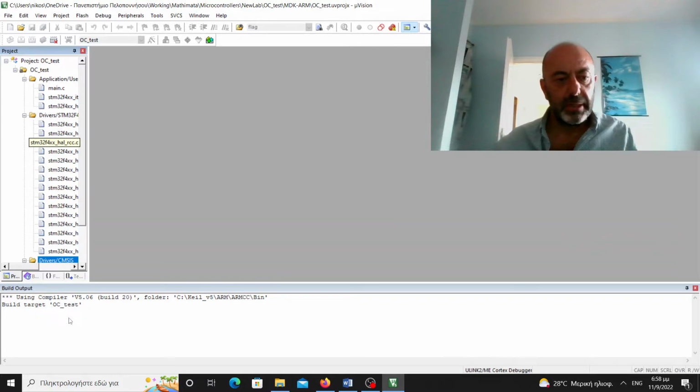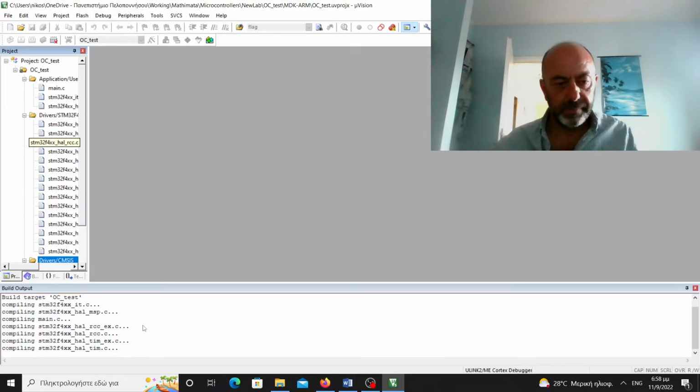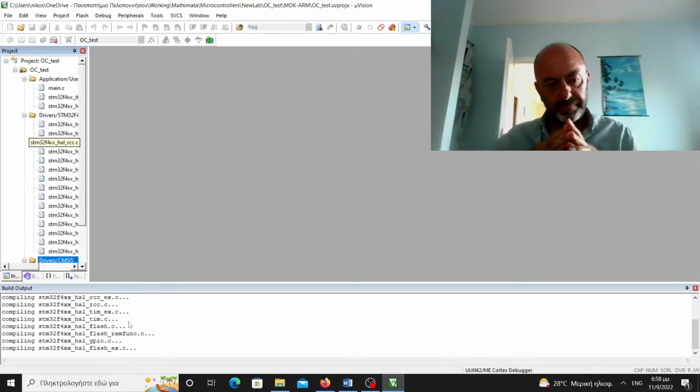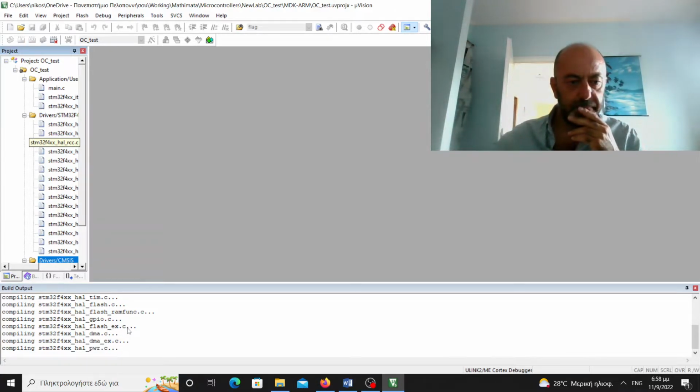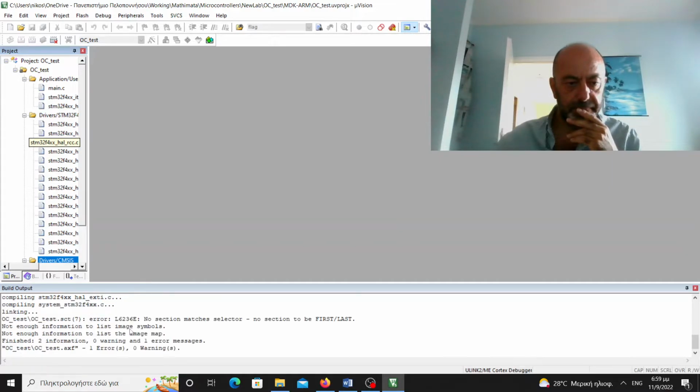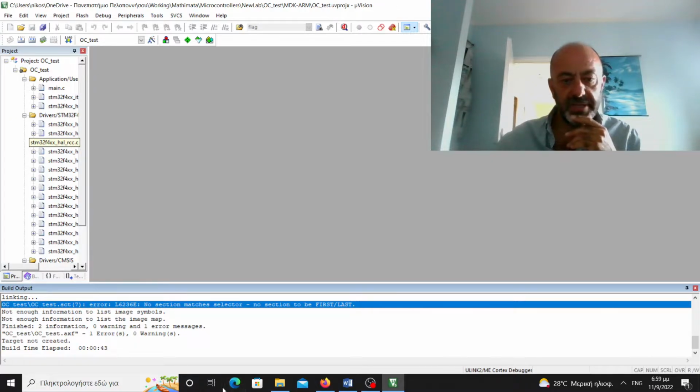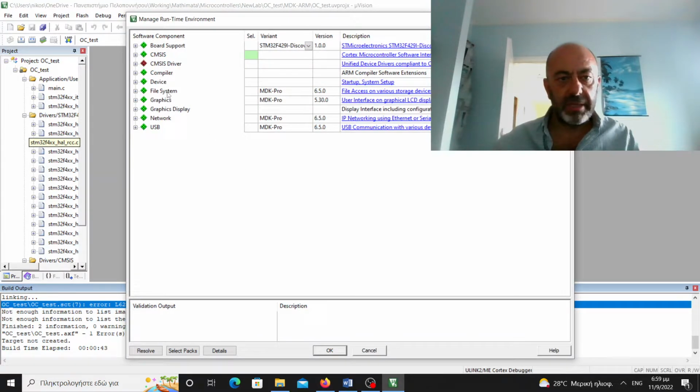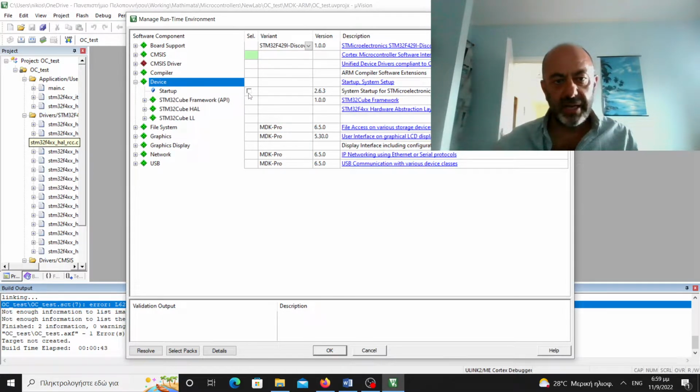All the messages are shown in the console at the bottom. Wait for a while. Okay, I see that I have the same error as I did in my previous video, which means that I have to go to the manage runtime environment. What is missing from the project that the CubeMX created was that with the start device, it didn't add the startup header files.